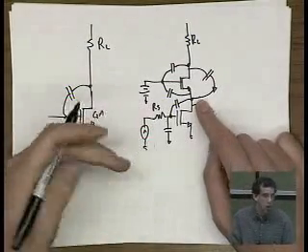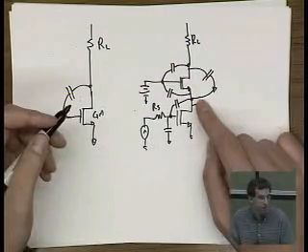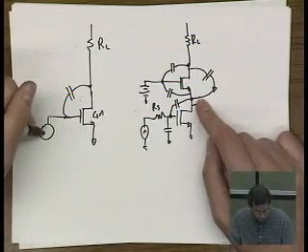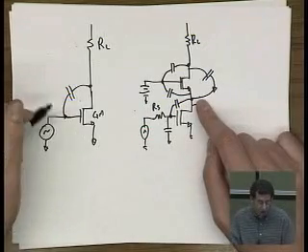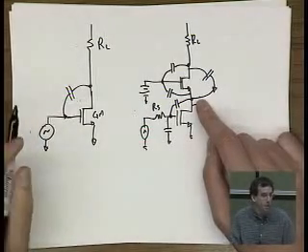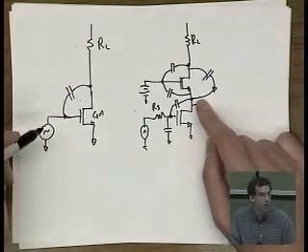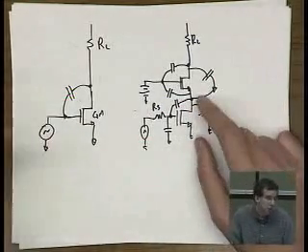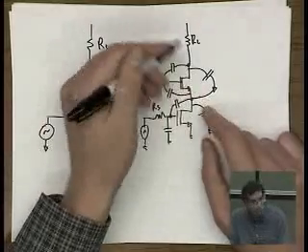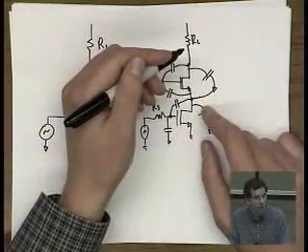So in order for the Miller effect to really happen, like if you just drove this node, you'd still have the Miller effect in the capacitance, but it wouldn't band limit you because it's being driven by a very low impedance node. Here, this is a very low impedance node. So yeah, there's Miller effect looking up that way, but it doesn't really affect you.